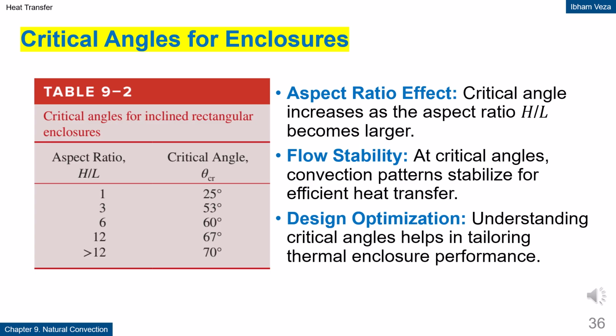Critical angles for enclosures. For each aspect ratio, there is a critical angle at which the flow pattern changes significantly. The larger the H/L ratio, the larger the critical angle. At certain angles, the system becomes more stable or more efficient in transferring heat. The concept of critical angle is important for enclosure design optimization. This shows that orientation and geometry are closely related.